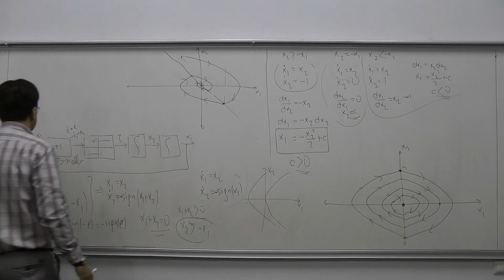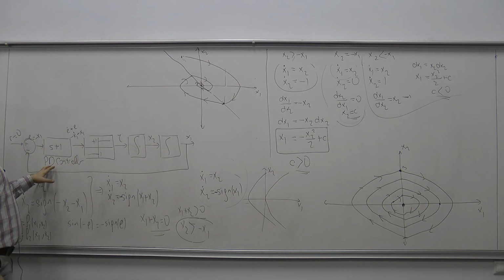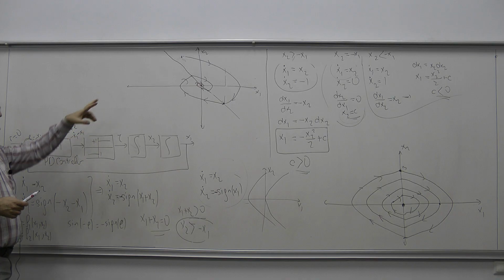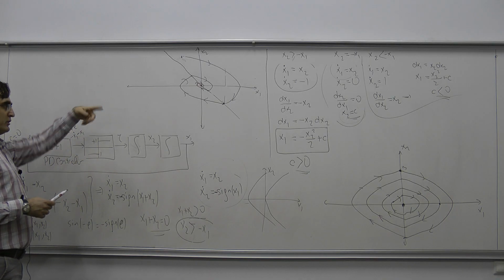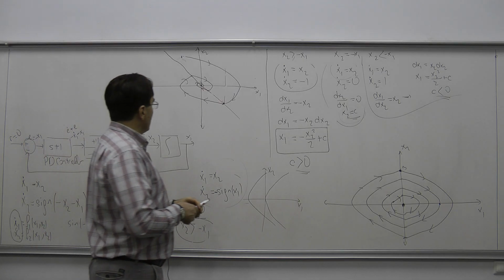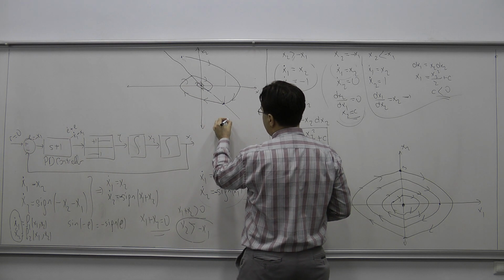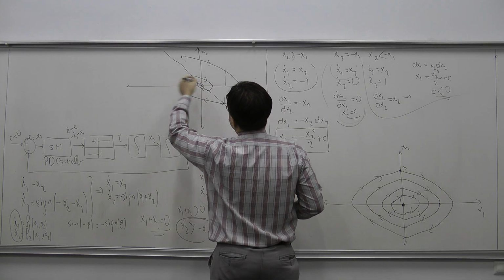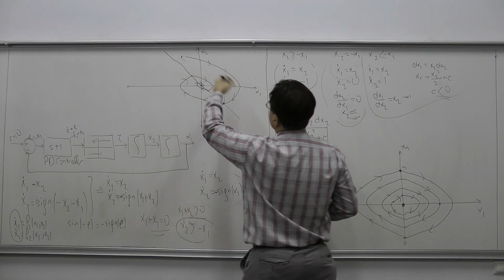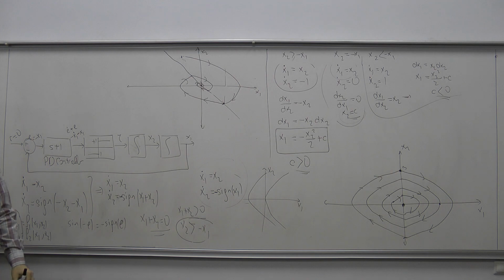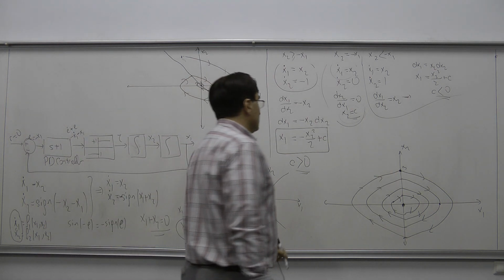Of course, sometimes when we try to put another controller here, we might make some mistakes. So here we see that if I put this PD controller there, I could achieve a convergence to the equilibrium point. What would happen if I started somewhere here? It would be the same. It really doesn't matter. Wherever we start now, we're going to end up at the origin.